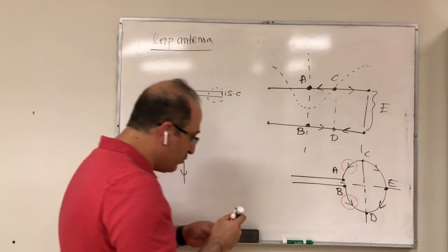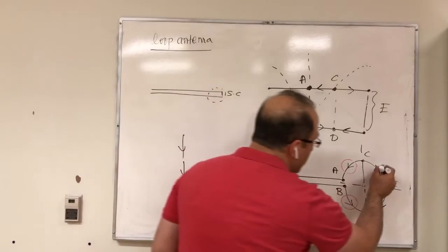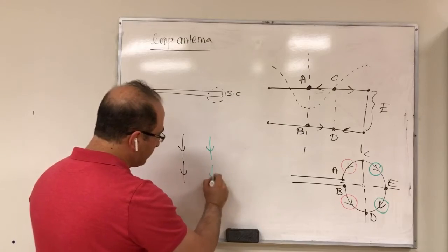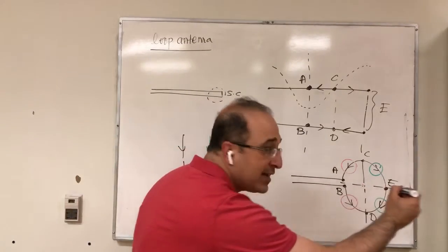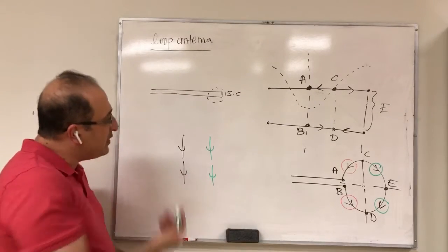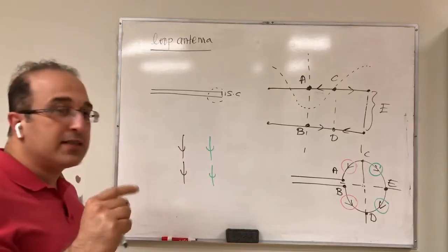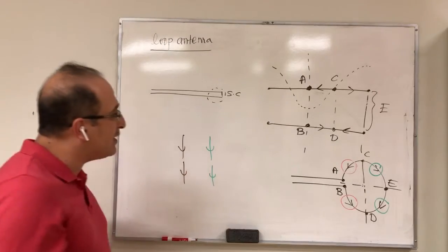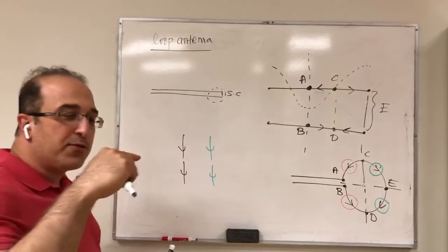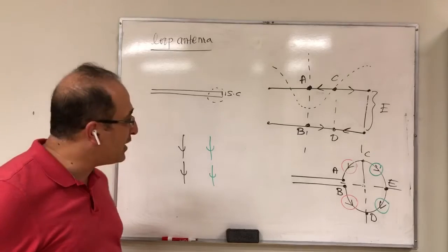And then you might think of this piece of current and this piece of current as another dipole antenna. So when you are on this axis in the far field and you look at that, you might think of it this way. So now what do you have? When you are on the axis, you essentially see two dipole antennas that are helping each other. So you're going to get lots of radiation when you are on this axis from the loop antenna.